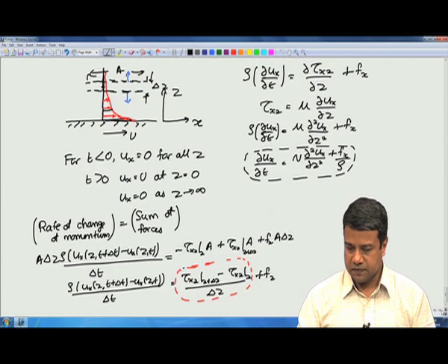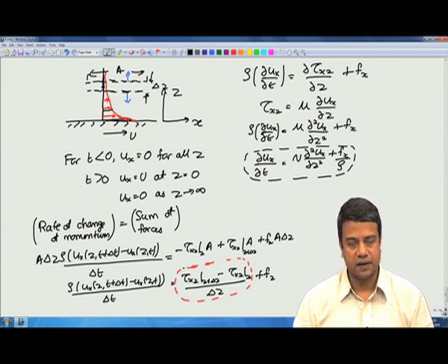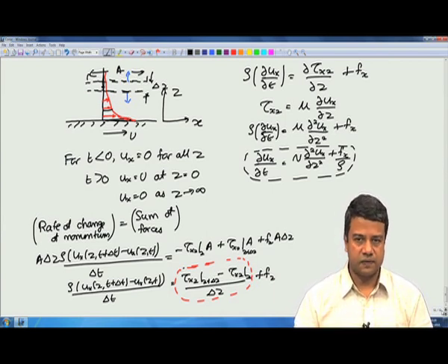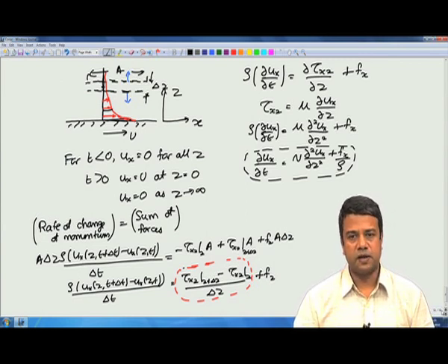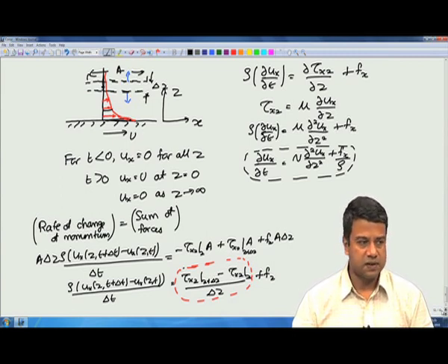Okay. So, we had solved this for momentum transfer as well. In that case, we had considered a surface, a fluid adjoining a surface, an infinite fluid. Initially, everything was at rest, and at time t equal to 0, the surface was moved instantaneously with a velocity U. So, for t less than 0, the velocity ux is 0 everywhere, and for t greater than 0, ux is equal to capital U at z equal to 0. Far from the surface, the momentum diffusion has not yet happened. If you go to a large distance from the surface, how large we will see once again, since momentum diffusion has not yet taken place, the velocity still has to be equal to 0.